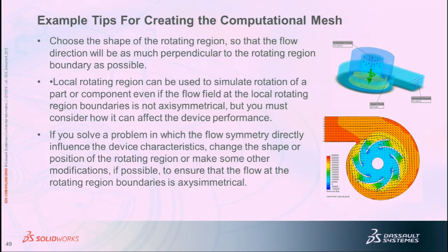So what you do is, just like the local initial mesh command, you create a SolidWorks feature around the blades, a big solid, maybe a cylinder block, same height. You want to go a little bit past the blades, I'll show you a couple of slides, to capture flow that's going around the blades. And you disable it in the component control command, just like I mentioned before, okay?